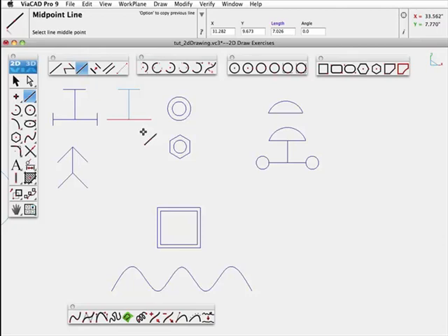As you create, you'll look at the circumstances and pick the tool that makes it easiest to achieve the results. And the Midpoint Line tool makes this much easier. And we'll use the same tool to create the ends. In fact, after the first is drawn, by pressing the Control key, you can click a single point and a duplicate of what you just drew will be placed. Notice we used the Midpoint Line tool, so the point that you picked was the midpoint designating that next copied version.